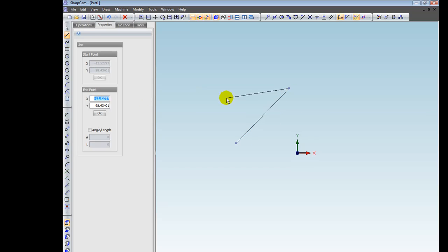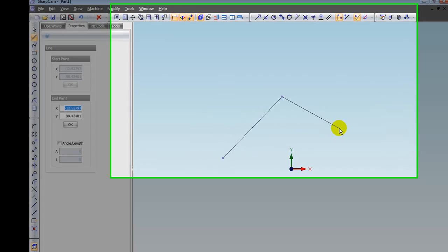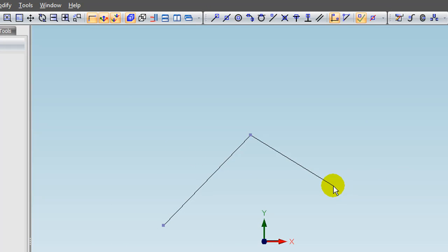It now wants the end of the line, and again we can either key in a value or snap to another line, arc or circle. There aren't any more, but whilst we're getting the end of a line, if I move the cursor near to a point which is perpendicular to the line, can you see what happens? There's a blue snap marker, a snap-perpendicular-from cursor icon is displayed, and the origin line that the snap is originated from is highlighted. That would be exactly 90 degrees to that line. There'd also be another snap perpendicular from there.